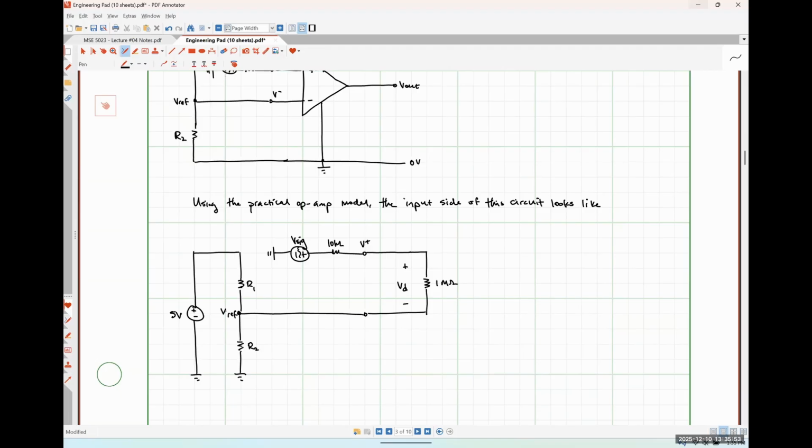So what I'm attempting to illustrate here is that if we choose resistors that hit our ratio, but we make a poor decision as to what the size of those resistors are, we're actually going to see that our reference voltage is going to drift as our input signal changes, which is a very bad thing because we're trying to compare that input signal to our reference voltage.